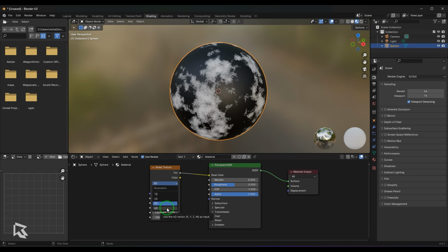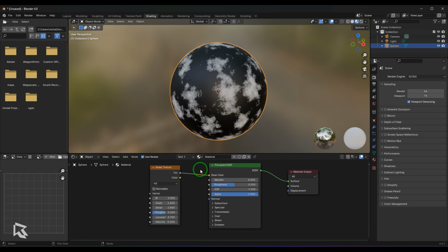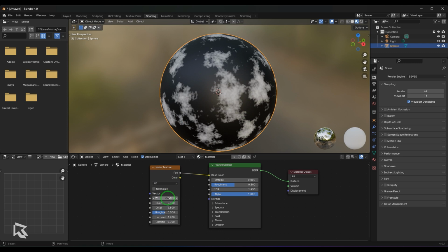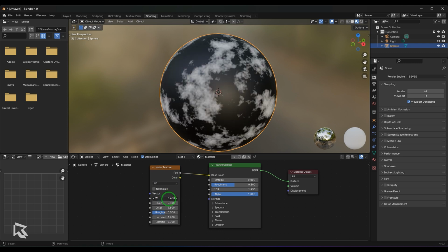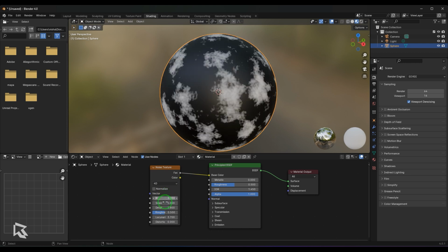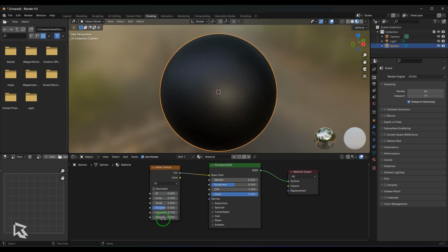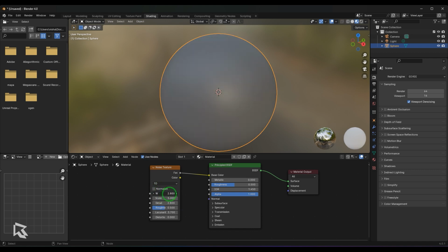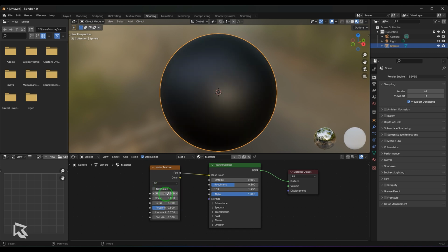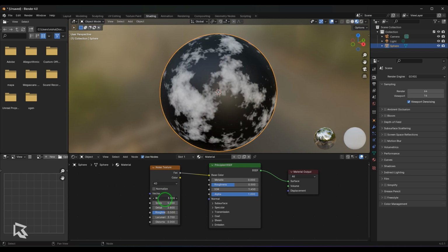So if I just choose 4D, then the new attribute comes here, which is W, which is the 4th dimension, time. So if I increase that value, you should be able to see there is sort of evolution of the texture, just like animating water. If I only pick 1D, then one particular value is applied here, and if I animate the value, it starts blinking. Maybe you can connect this one into a light for intensity, and then the light keeps fluctuating like that, okay? As one dimension does not represent the texture, right? So that can be used in that way. If not, the 4D has this W where you can animate it.